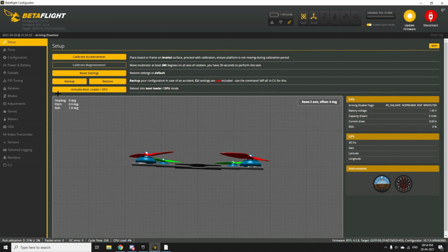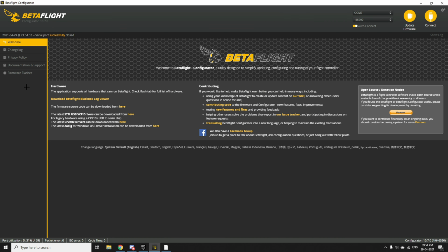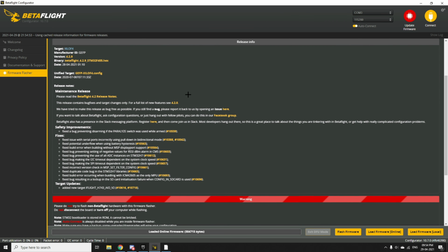First thing, when you open Betaflight 4.2 and above, it will ask you to apply custom defaults. Just say yes to that. I won't explain what it does. If you don't say yes to that, you'll need to reflash your board. By the way, this process which we just did right now is known as flashing.